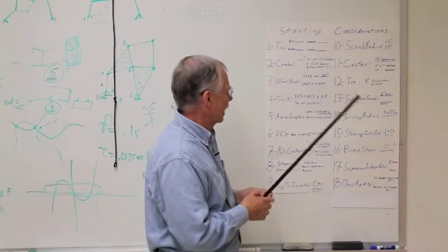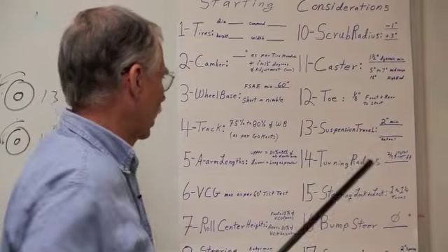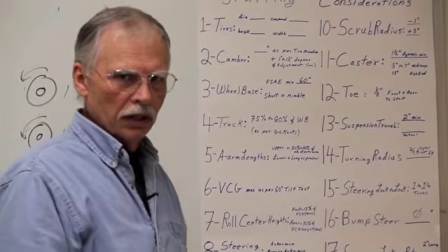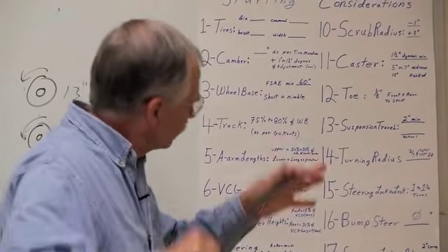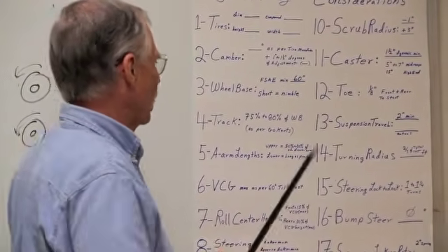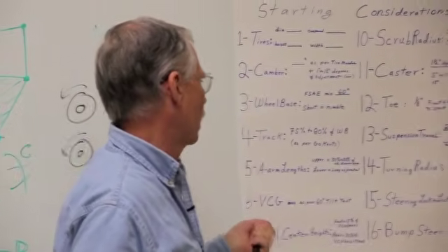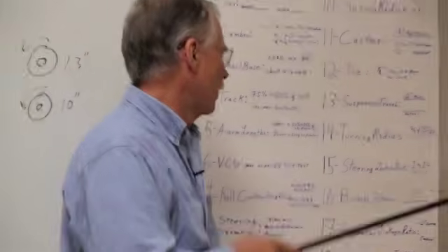3 inches, not a bad idea. Trying to get really close to 2 inches, depending on the courses, they do have dips, they do have unevenness. You do need suspension travel so that the wheels can stay in contact with the course at all times.